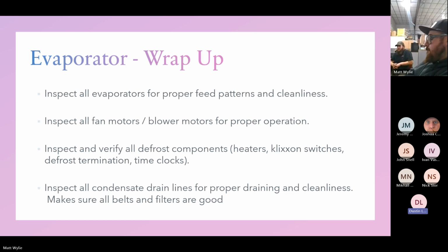Actually, we had one guy, and this wasn't here at Coltech, say, "Oh yeah, the time clock's bad. I put it into defrost and it stays in refrigeration." And he changed the time clock and left.